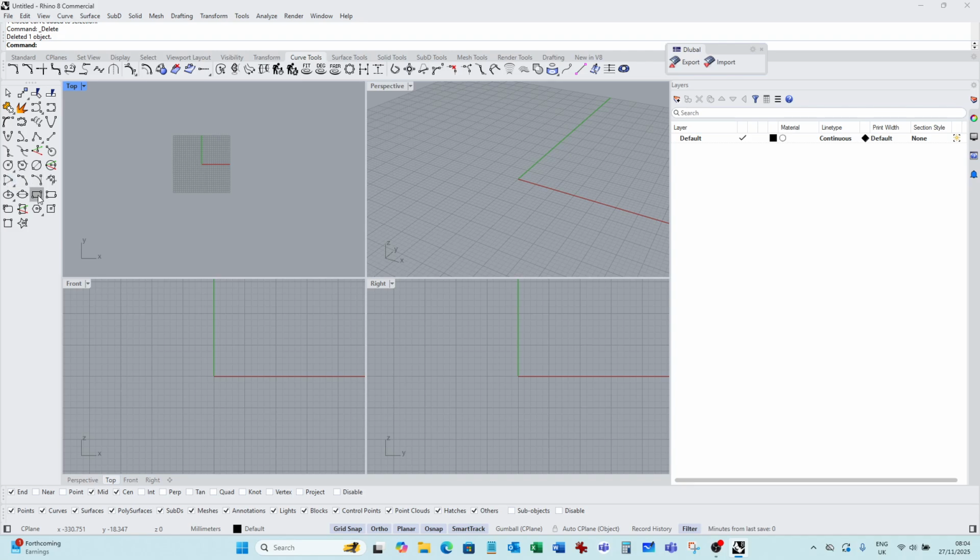We're going to type rectangle. We're going to click on the origin. We're going to stretch to the left 20123 comma 12123. Okay, let's see if that looks a bit better. Okay, that's a better rectangle.